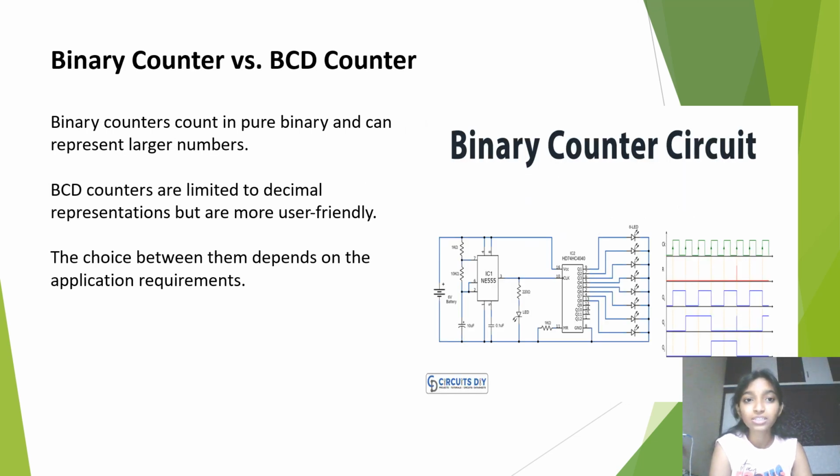Binary counter versus BCD counter. Binary counters count in pure binary and can represent larger numbers. BCD counters are limited to decimal representations but are more user friendly. The choice between them depends on the application requirements.